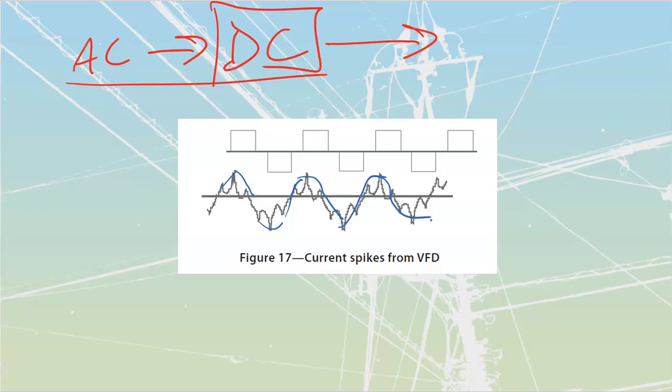The next part of your binder over here really starts talking about performing troubleshooting. Performing troubleshooting of power quality issues is horrendous. It is one of my least favorite things to do out there because it's so hard sometimes to track this stuff down, particularly if you don't want to spend thousands and thousands of dollars on high-end equipment. In a lot of cases, you can rent good quality meters through wholesalers, rental places, or other companies that will loan you stuff for either cash or a case of beer or whatever. But you are hopefully going to be able to get your hands on some sort of power quality analyzer.